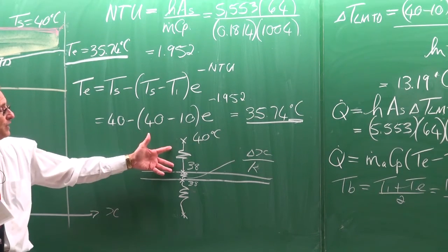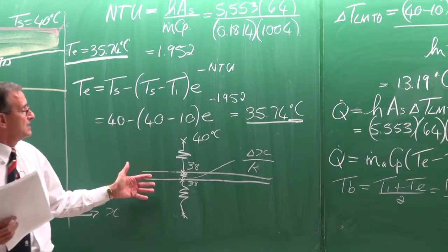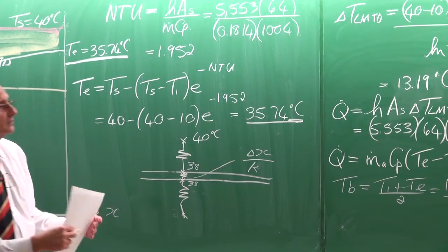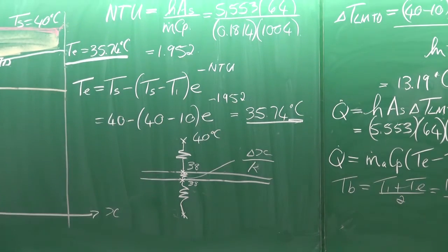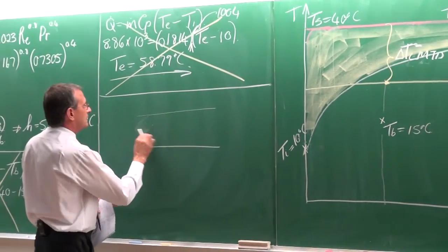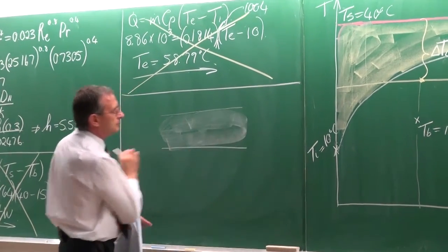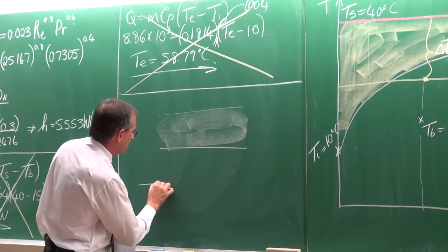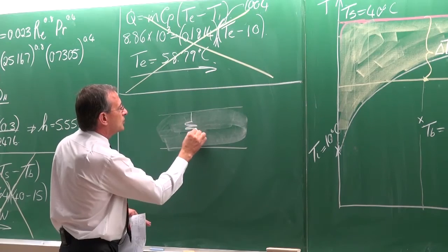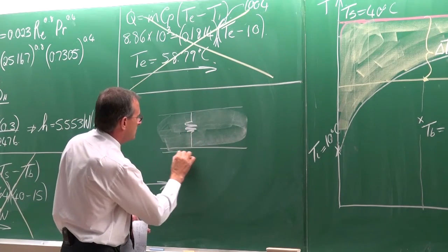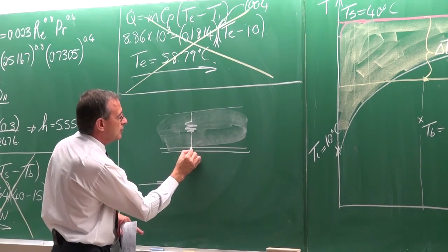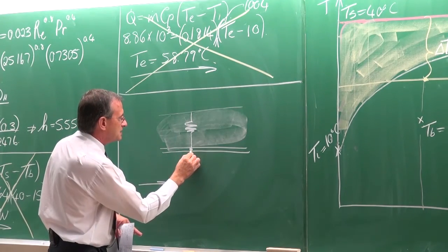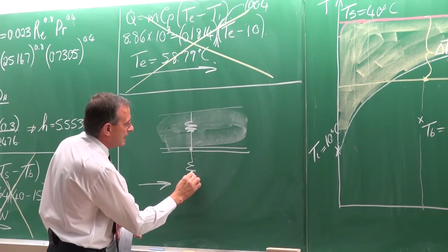It's the same principle now with insulation. So if you want to insulate this duct, let me draw it here. Let's suppose here's the insulation material, and here's the air going through. Again, we've got the resistance terms for the insulation material, for the galvanized steel or the plate, and then for the air.